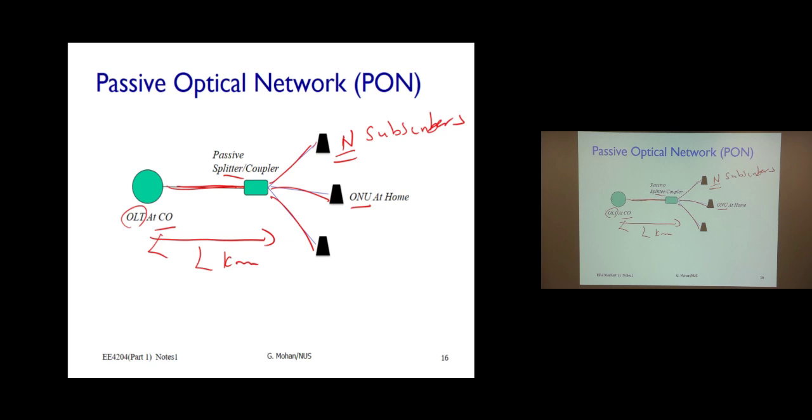So now there is two-way communication. In the downstream side, it's a broadcast. Whatever is sent from this CO, the OLT, the line terminal will transmit. Please note that once it's transmitted through optic fiber, the transmission signal is in optical light form. Inside the router or our computer, the signals are stored and processed in electrical form. But once it is transmitted, the electrical signal is converted to optical pulses or light waves, and it will traverse like light through the fiber.